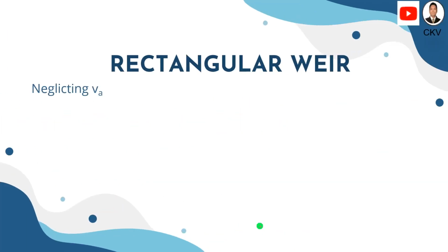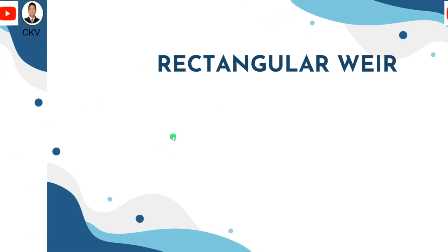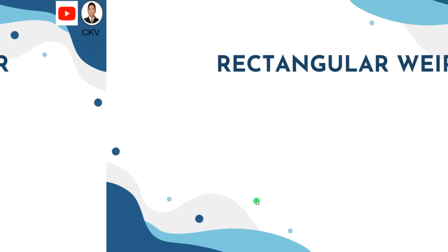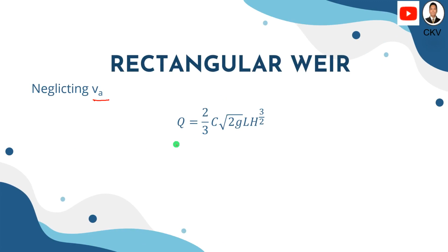Next, if we are going to neglect the velocity head of approach, it means that we ignore Hv, so this will be 0. What will remain is this equation: Q, or the discharge, equals 2/3 C times the square root of 2g times L times H raised to 3/2.